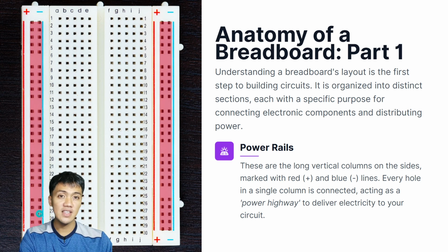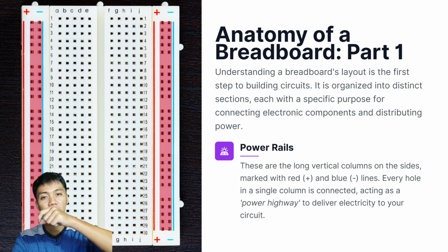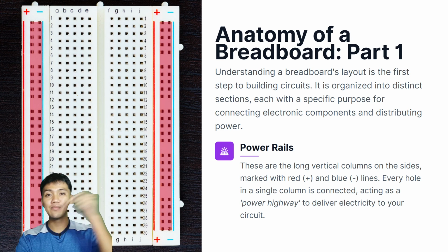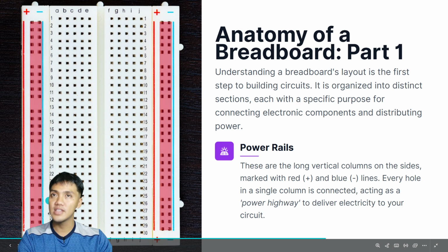That simplifies things because you can just plug one component in the positive rail, and then the other end of the component will return back to the negative rail. So these long lines at the very edges, the outside of our breadboard, are what you call your power rails. They are connected in this manner.